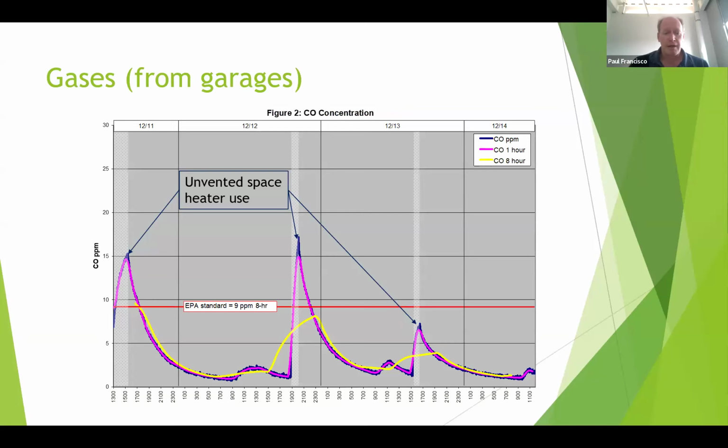We were measuring combustion products indoors from people using unvented space heaters. At that point, we weren't doing as much in the way of PM 2.5. Certainly our group, we weren't measuring PM, so we don't have those numbers. But where you see this dot shaded thing, that's when the unvented space heaters were on. And we see the carbon monoxide rising pretty strongly in each of those. What we also see is that we have these things unrelated to the fireplace. And so we thought that was interesting.